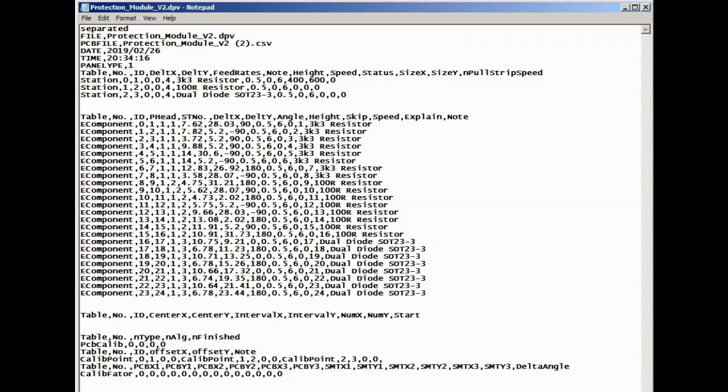This is derived from the data that's in the CSV file. Now, as long as you get the component information right within the CSV file, then this will all be correct and you won't need to do much more with it. The only things you're likely to need to change are the size columns. If you look at the second and third feeders, they're set to 0, but in the first feeder they have values that don't make sense.